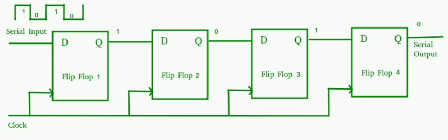TTL, transistor-transistor logic. TTL circuits are classified as totem pole logic (active pull-up), tri-state logic (high impedance logic), and open collector logic (passive pull-up). Tri-state logic is used in bus-oriented systems. Totem pole logic does not provide wired logic. The advantage of active pull-up over passive pull-up is reduced power dissipation and increased speed of operation. Any floating input of TTL is considered as logic 1.